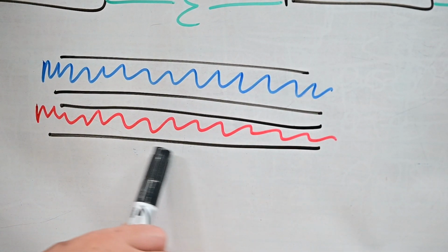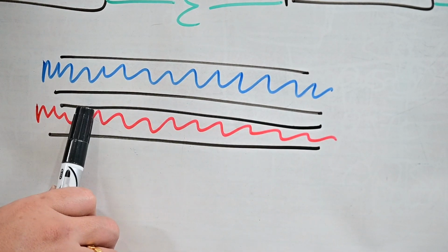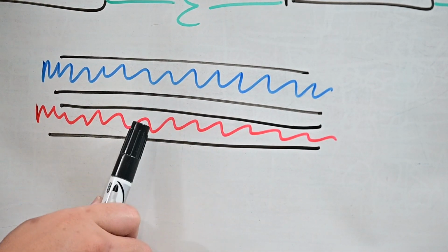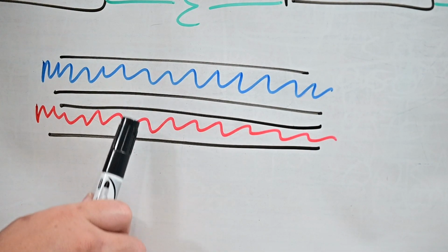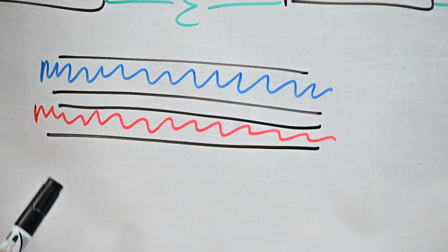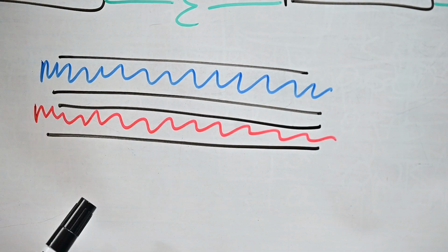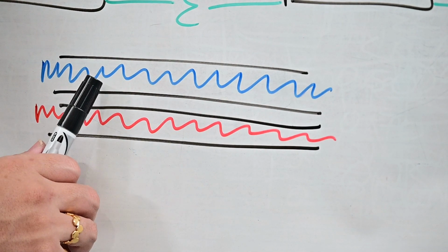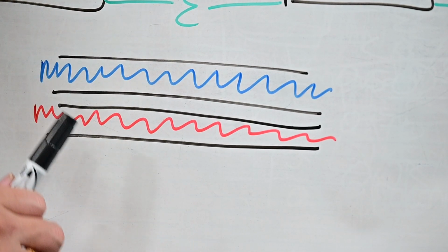The black portion is the PVC insulation. Is there any leakage between these 2 conductors? The minimum requirement from the regulation is 1 megohm. If anything is below 1 megohm, it is recommended to be replaced.